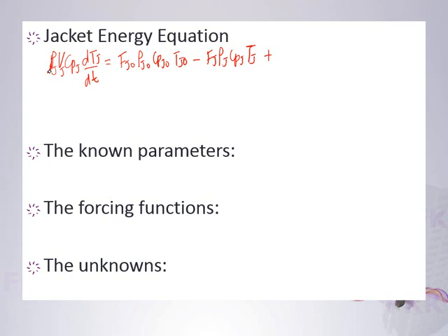Now as a coolant, you want to cool off the system, so the energy will be received by the coolant, so it's plus UA H. H is the heat transfer area, the area that is in contact between the cooling water and the reactor. Still hot minus cold, in this case T minus Tj, then you'll be okay.